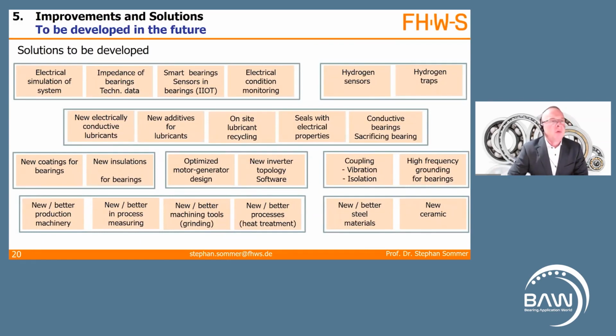Now let's go to solutions and improvements that we have to develop. There is electrical simulation of the system, the impedance of bearings. My idea is to have technical data showing the impedance of a bearing as well as of a dynamic load. Smart bearings and sensors, industrial Internet of Things. And the sensors would enable us to electrically condition monitor the bearings. So these are pretty low-hanging fruits. These are solutions in the market.